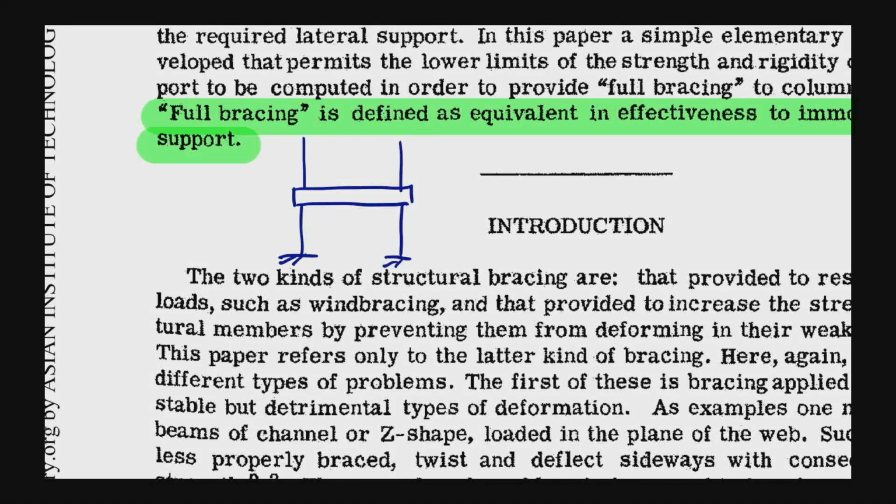You have a sort of building, and your structure might experience lateral force caused by the wind or the earthquake, and you have the brace installed in order to control the lateral drift, in order to enhance the capacity of the structure against the lateral motion or lateral excitation. You apply the brace like that.